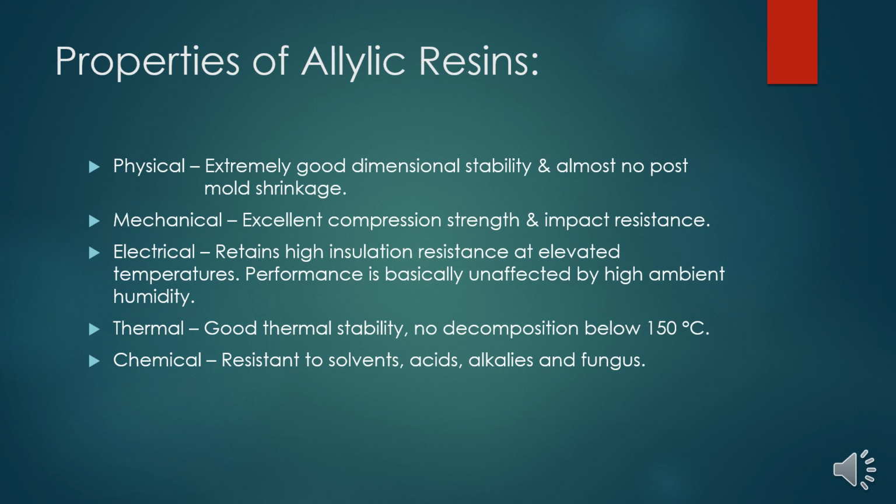Electrical properties are it retains high insulation resistance at elevated temperatures, and its performance is basically unaffected by high ambient humidity. Its thermal properties are that it's good at thermal stability and has no decomposition below 150 degrees Celsius. Its chemical properties is that it's resistant to solvents, acid, alkalis, and fungus, allowing for it to have many applications.